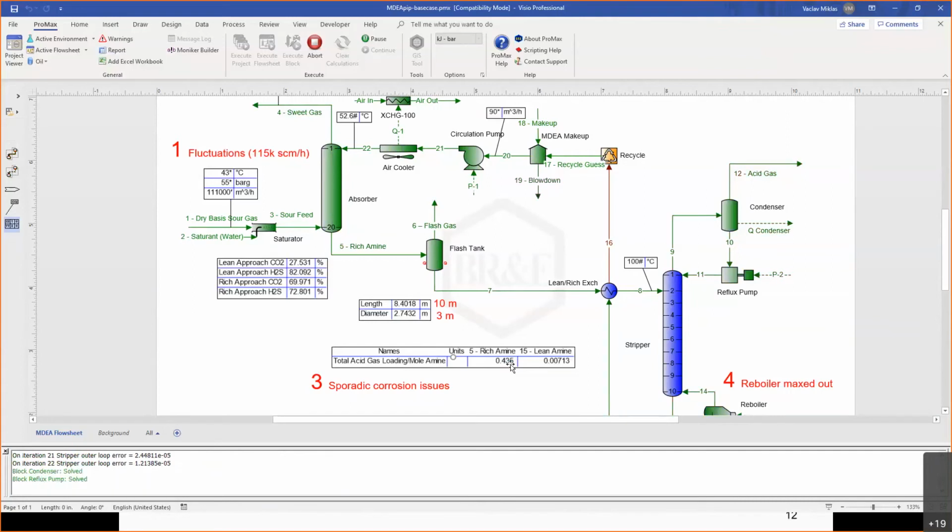To some extent, this is kind of mitigated by the fact that we are using piperazine together with MDEA, because piperazine, on the other hand, has a rather high heat of reaction with CO2. So these two kind of balance themselves in this specific blend. But overall, MDEA and piperazine is very popular, and I've just told you the reasons why that's the case.